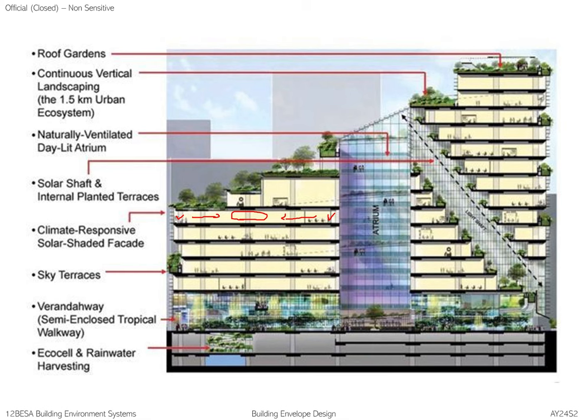So if you contrast this versus this plate now, you can see that it has diffuse daylight, and it also has diffuse daylight on the other side. So the reliance on artificial light is actually very low in this series of spaces. So within this massing itself, you can see very different explorations of different ways office spaces can be done. Without this diagonal light shaft that he has used to cut through the space, the floor plate is actually quite deep.